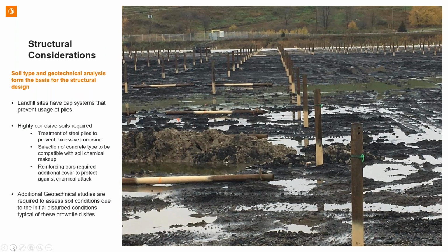When you're dealing with various brownfield sites, you may have unknown or uncertain soil conditions. In the case of landfill sites where you have a cap system, you certainly cannot use a piling system, as you obviously cannot puncture the caps.